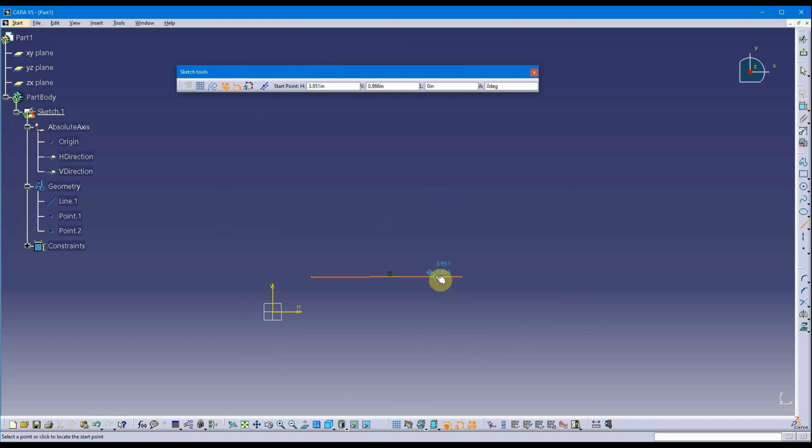You see two concentric circles that does not have a solid center. That is creating a coincident constraint. But it's not a point-on-point coincident constraint. So that is creating a constraint. Let me create that. And I'm just going to pick out here in space.